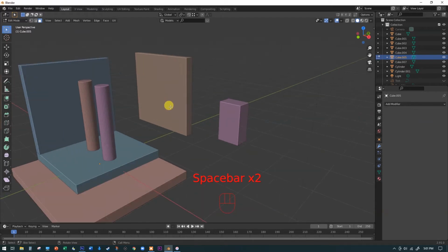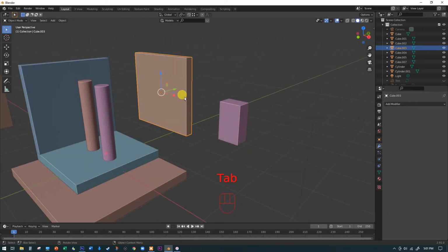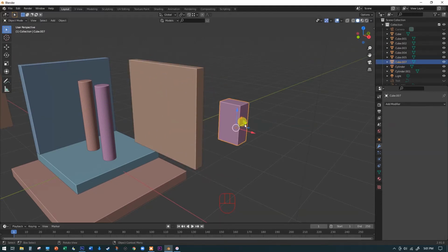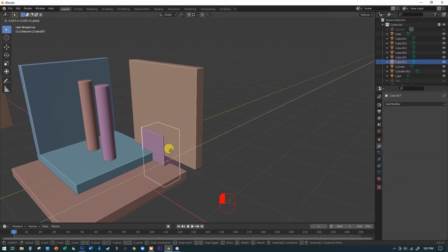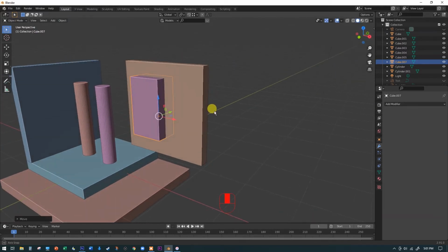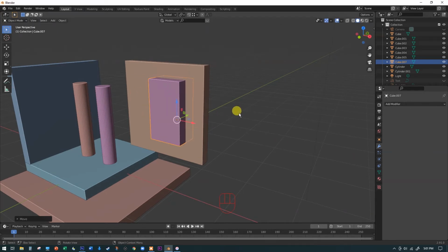This is also a great place to introduce the idea of using Boolean operations to make doors and windows. So I'm going to tab out of that one and grab this one over here. We'll move it a little closer to our model. And then I'm going to use this little block to create a window or a door. So I'm going to pull it up into the shape here and make sure that it's poking all the way through. Here, I'll make it a little bit more center there. And remember, we're taking this shape out of the brown one here.